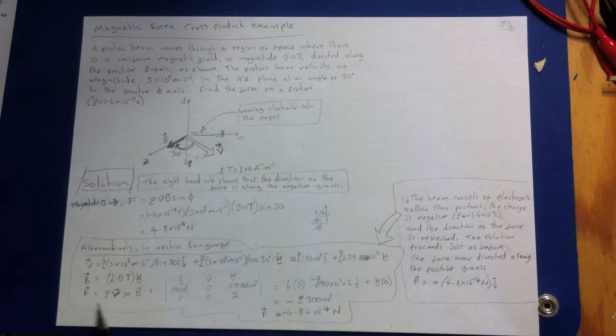And then for the force, we're going to use the cross product. We just use the matrix determinant here. Finding the determinant of a matrix, we write down the i, j and k, and then we ring around the i component, putting a ring around there and a ring around there, so we're going 0 times 2. Obviously the i component then becomes 0.